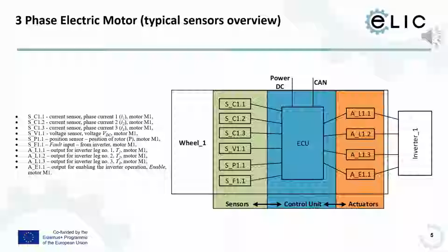So we would have sensors measuring back: current sensor 1, current sensor 2 and current sensor 3. And then there are some mathematical and physical laws with which we can check that the currents are correct. Which means that when we control a motor, there is a Kirchhoff law, for instance, that the sum of the 3 phase currents should be around 0.